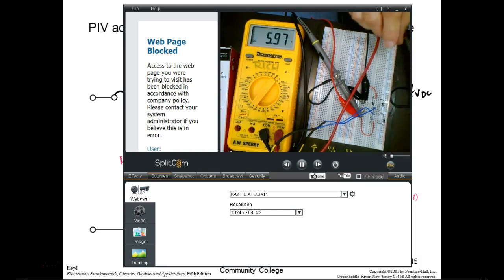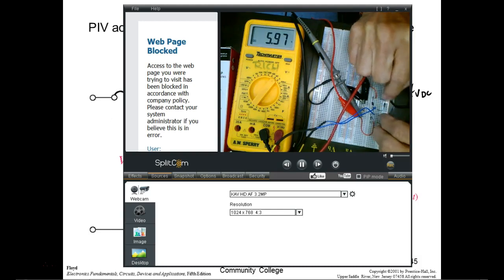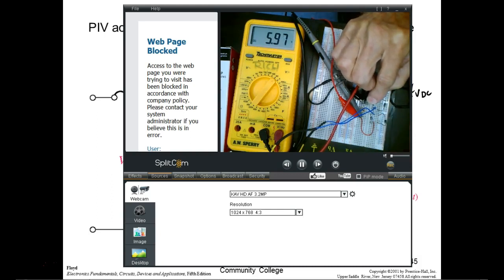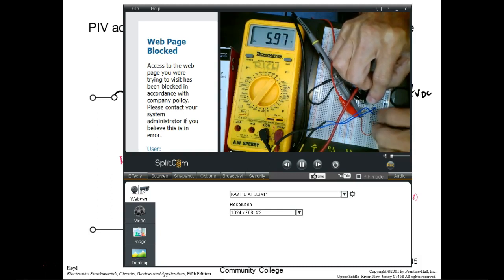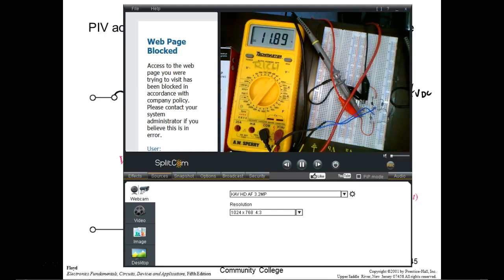Then we usually assume what? I still got a halfway rectifier. So if we end up with about half the voltage that we calculate, then we assume that it's what? Open. And also in a full wave rectifier, if one of your diodes shorts, you have a short circuit. So hopefully it's going to start blowing a fuse in your transformer. If it starts blowing, then either the transformer is shorted, or you've got a load that's shorted, or you got a shorted diode, and we'll show you how to figure that out too.